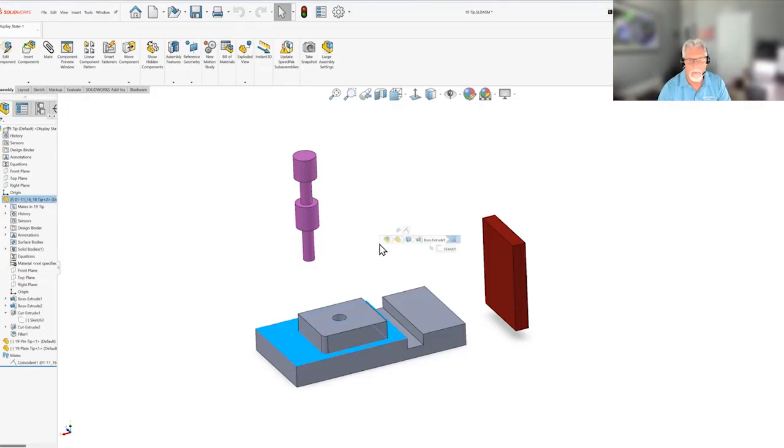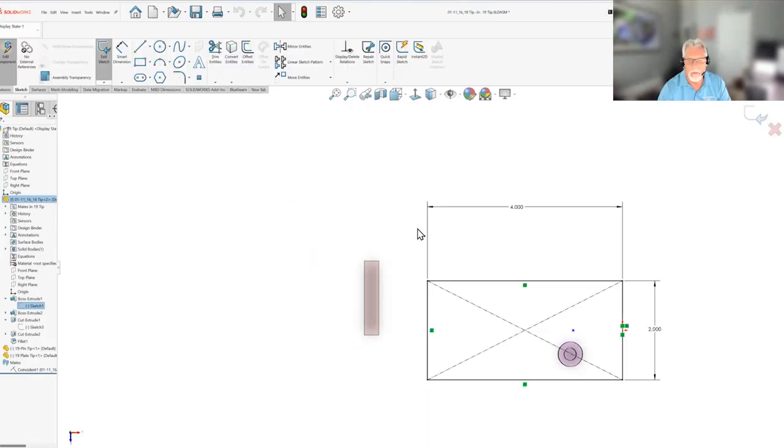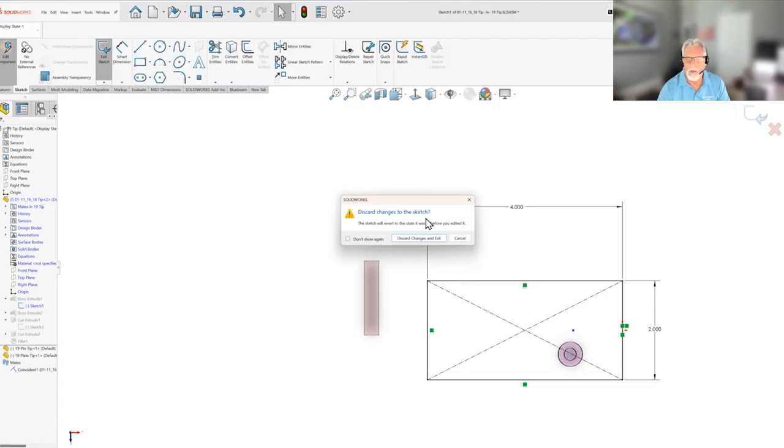So what I do now, when I select it, I hit the D key, that brings that up here. So if I want to edit the sketch, then I could just go here, then I've got my sketch right there. And now if I hit my D key, I can go ahead and say cancel, or I can say okay, accept whatever I've got done. So that brings that up there, so I don't have to go up and complete that up in the corner up here.